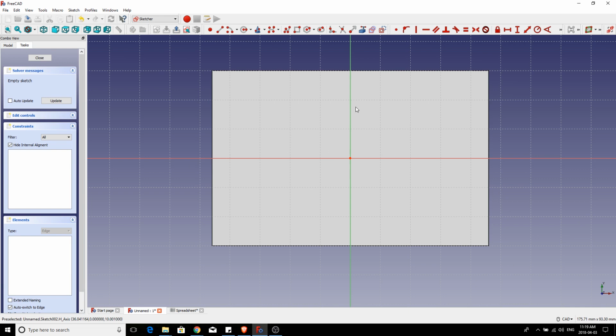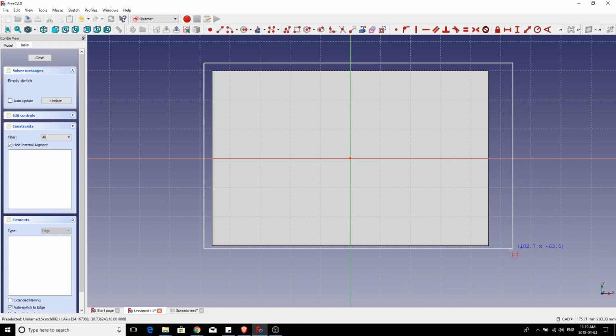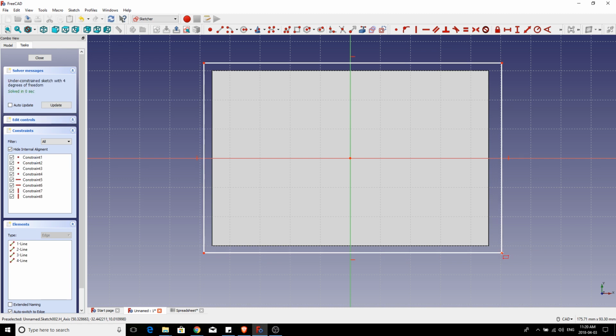And so there's the top of our box, right? This is the pad that we created visible right here. So with no further ado, let's go ahead and throw a rectangle on here as we've been doing all along. And then we're going to see how we can do our constraint on this thing. So in order to do this properly, parametrically, so that this rectangle we're making for our pocket can also change based on our credit card changing, well, we need to make sure that our constraints get applied to that credit card shape. But right now, we can't actually see the credit card shape. And the reason why is because the pad is getting in the way of us viewing this.